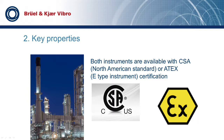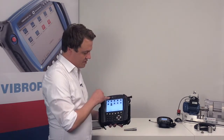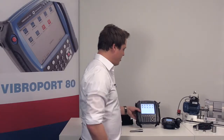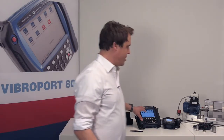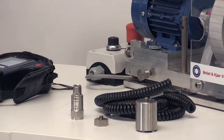For such a purpose, we have both instruments available with special certificates. The instruments can either be delivered with a North American standard, which is called CSA, or according for hazardous areas in the European region, ATEX. Both instruments are available with these certificates, and if you look on the instrument, a small E indicates that it is an ATEX instrument. However, do not forget, in your hazardous area you have a complete measuring chain. So that means that not only the instrument has to have ATEX, if you are in the EU, it also the cable, the complete measuring chain, that means cable, sensor has to be ATEX approved.